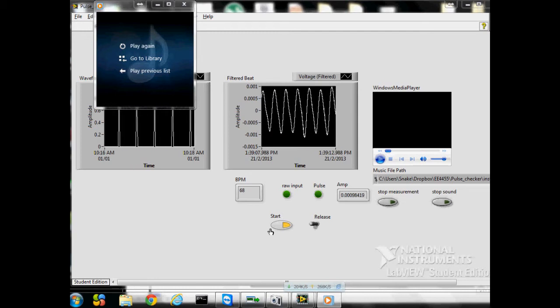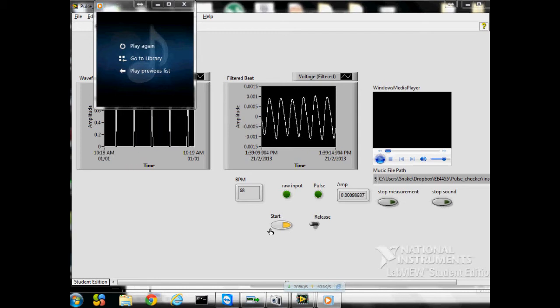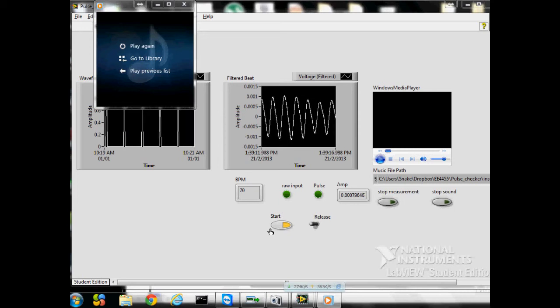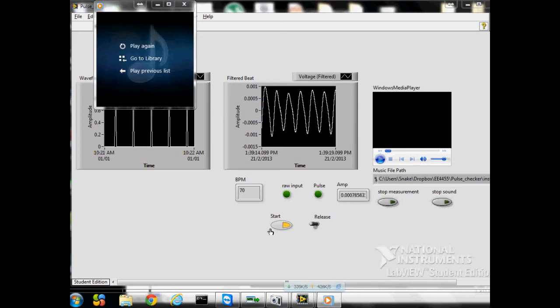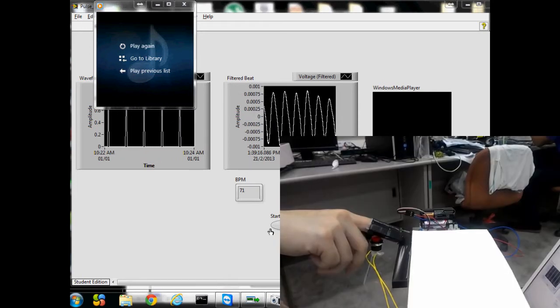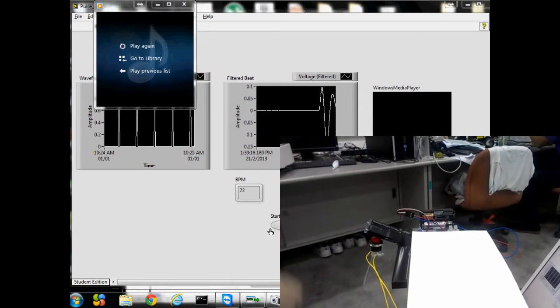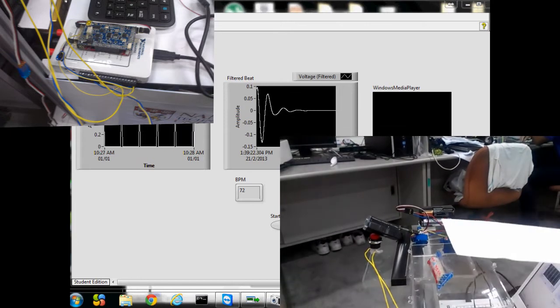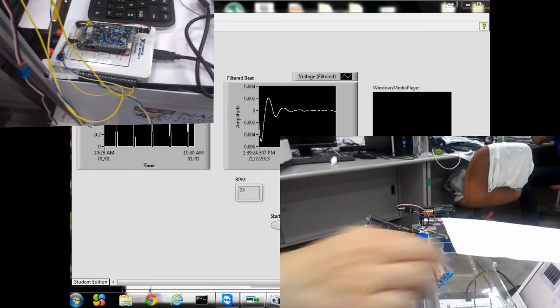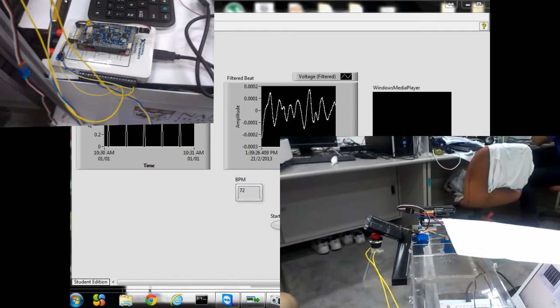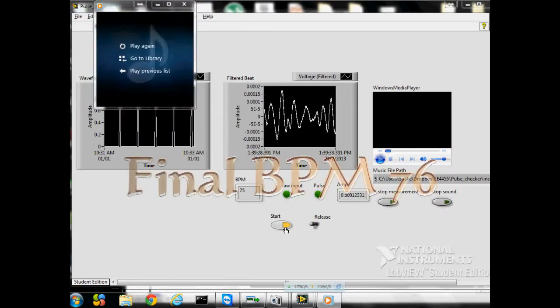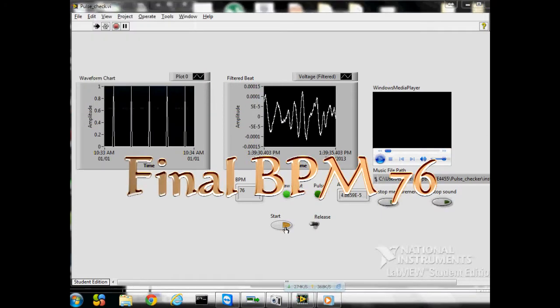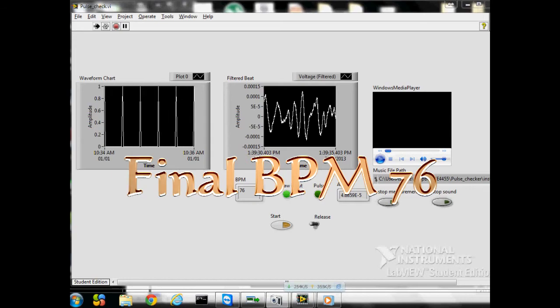Next is to release the medicine. That's the tricky part. For some reason, my DAQ can't output 1 millisecond based state changes at any of the output pins. So I have to use the myDAQ analog output together with an Arduino chip, which is preloaded with ADC input converted to a 16-bit PWM function to give the correct servo output.